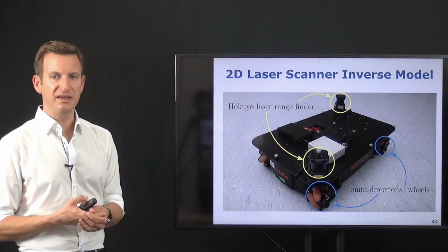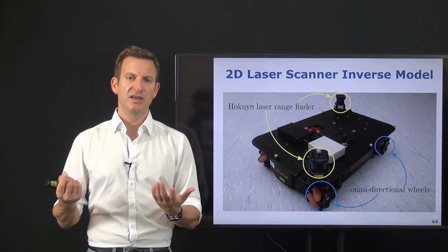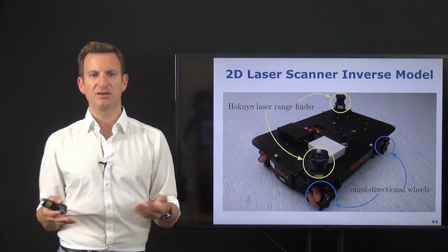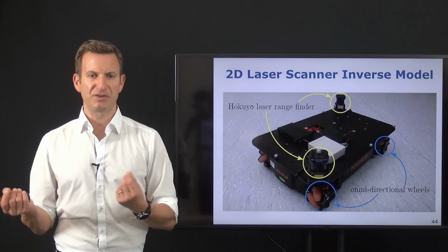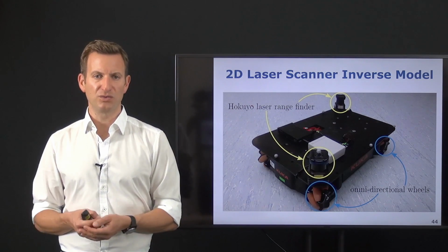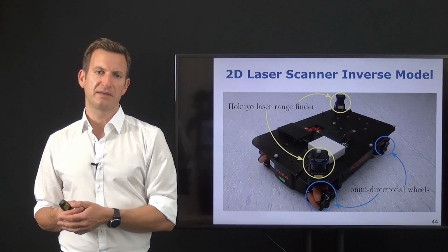So we start with the laser scanner example. Laser scanners are typically rather precise sensors, especially if you talk about, let's say, a grid resolution of 5 by 5 centimeters or maybe 3 by 3 centimeters, which models the environment in a rather fine-grained fashion and is typically totally sufficient for doing indoor navigation, for example. Then the sensor is typically more accurate than this grid resolution.